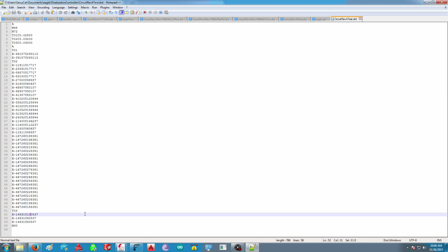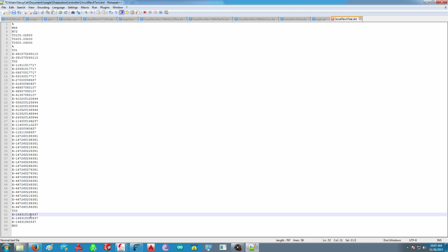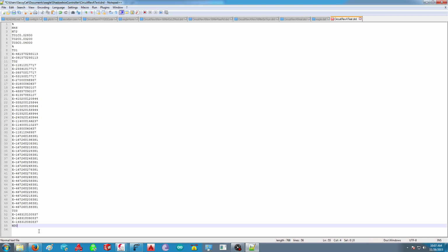And in here, oh, see, look. FlatCAM is looking at this and saying, oh, okay, y-axis, 1.0053 mil. Well, that's obviously not what we want. So what we're going to do is give it leading zeros so that FlatCAM has the same number of digits for each coordinate, x and y, so that it knows how to interpret the data.